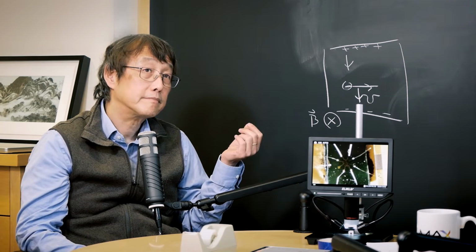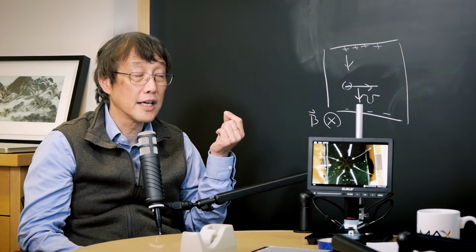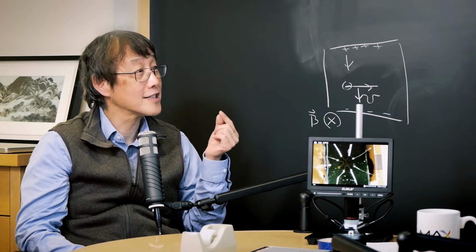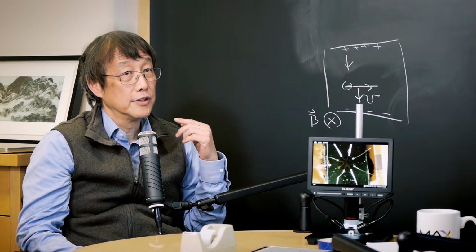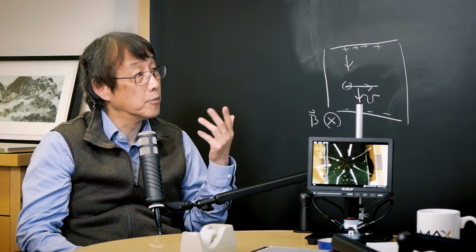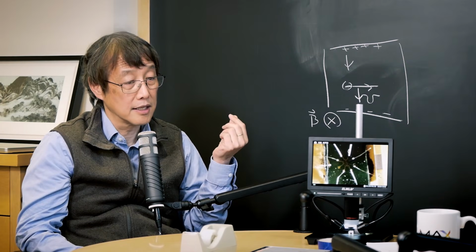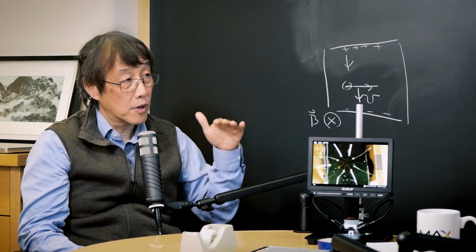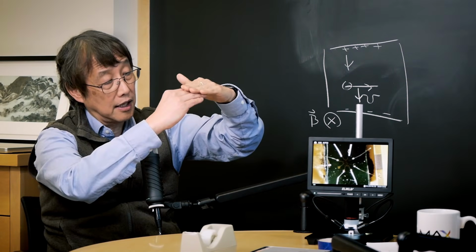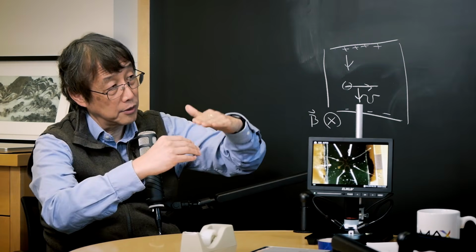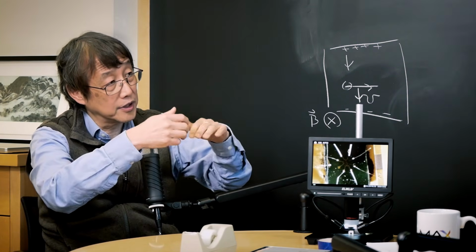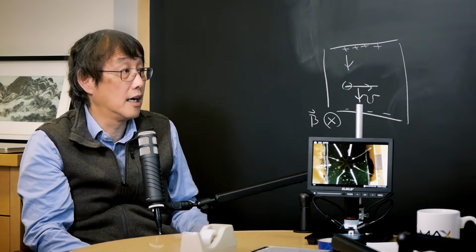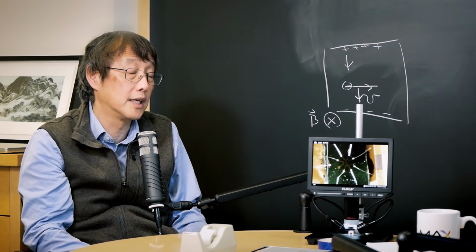But then the next thing is that one has to come up with how to confine the electron into 2D, and that requires technological development. You know that the modern transistor, the CMOS, complementary metal oxide semiconductor, works with the gate, the gate oxide and the channel. Within the gate, you can pull the electron near the surface and confine it at the surface. That's how you can make this MOSFET work.